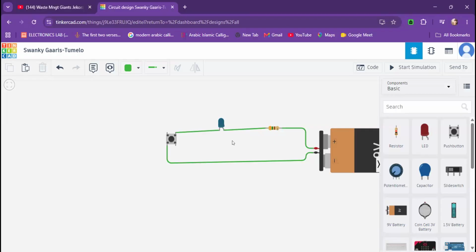As I press on the simulation, the light comes on by itself, but I thought we have to use the switch in controlling the light. If the light is on by itself, check the terminals you use for the push button.